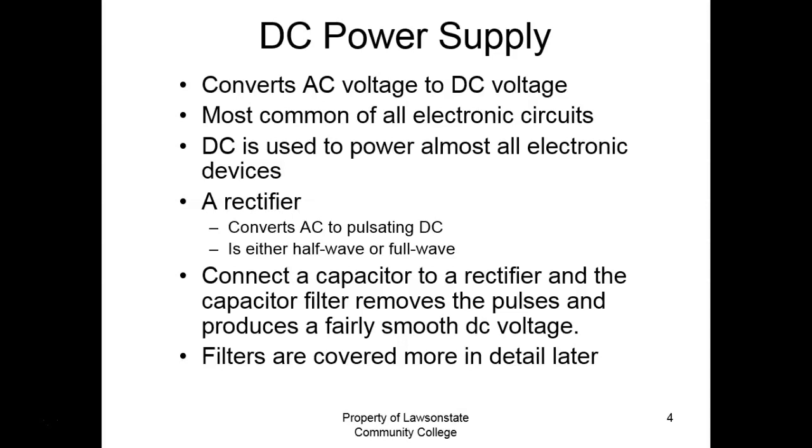I don't know if there's a current rating on these. I know the 5 volt regulator that's on this thing is rated at 5 amp. And this is the one they blow all the time. It's a 5 volt supply. So this one's 5 volt regulator has gone out. It's not gone, it's there. So I know right off the bat to fix this thing, all I have to do is replace that regulator and then it'll be back up and running.